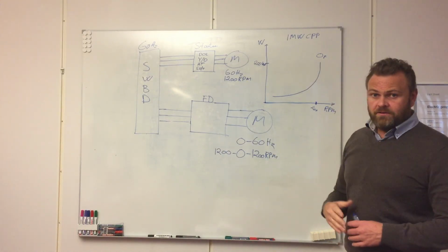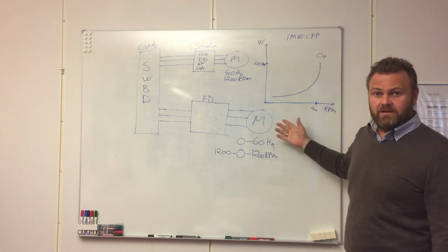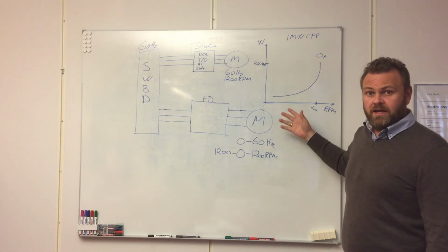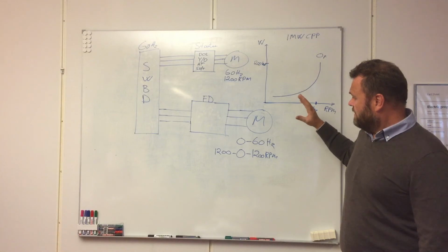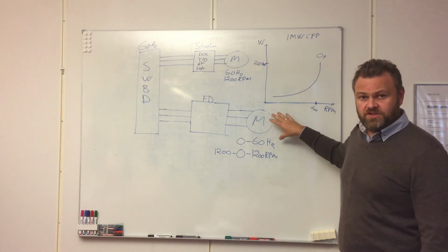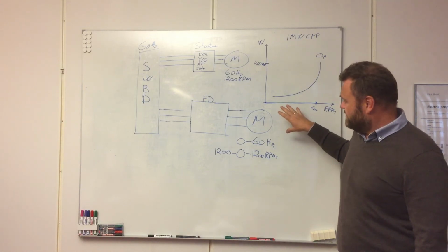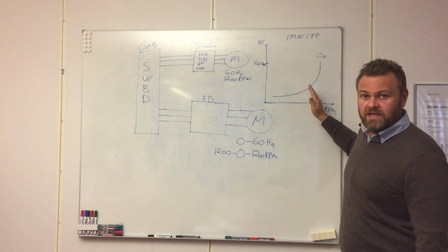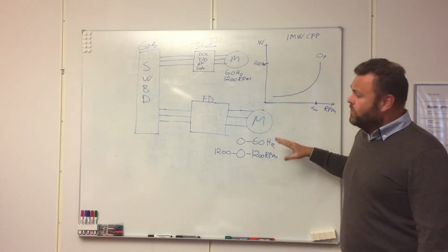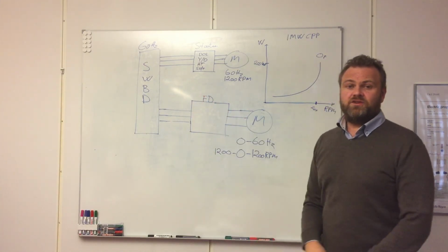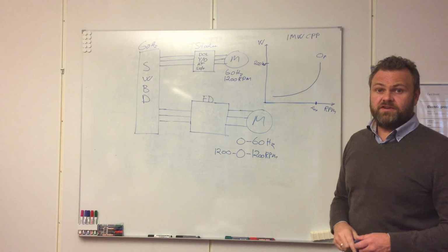But for a tunnel thruster, a propeller that is in use many hours, and a big percentage of the usage is propeller idling or between 0 and 50% load, well, then you should start to look at whether maybe it is good to have the frequency drive.